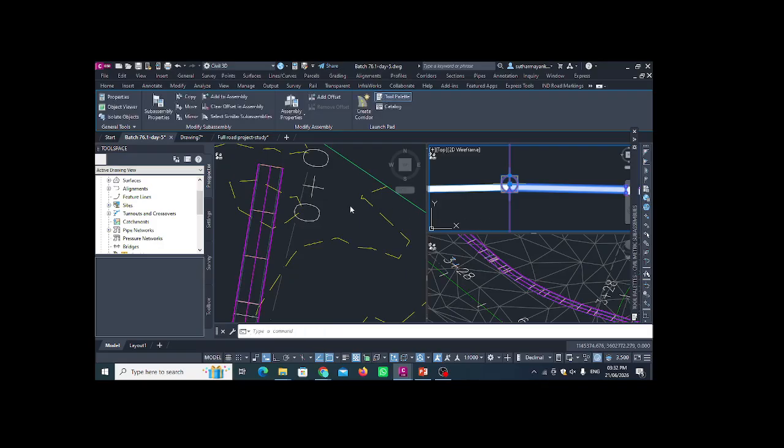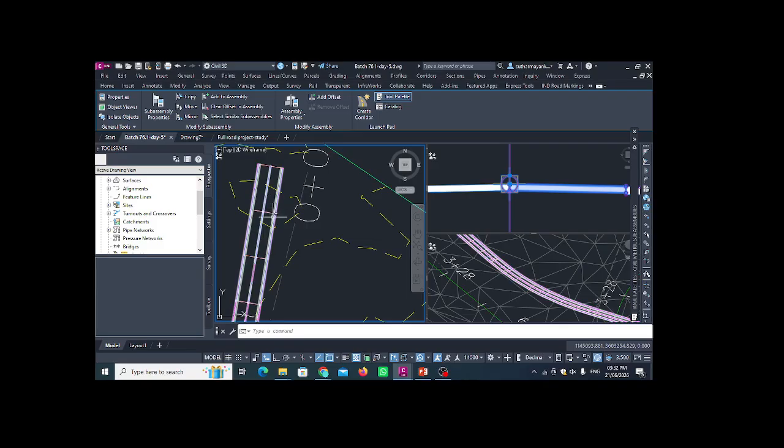Now, I set it so my grade is the same. If my assembly is joining here, I want to set that my assembly joins here on this offset. But I need that the grade that I provided here will be maintained throughout this line. Only the length is going to be changed.